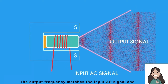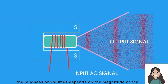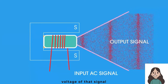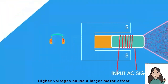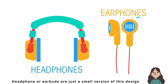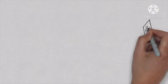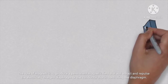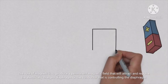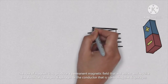The output frequency matches the input AC signal, and the loudness or volume depends on the magnitude of the voltage of that signal. Higher voltages cause a larger motor effect. Headphones or earbuds are just a small version of this design. They work on the same principle as this theory. Magnets are used to produce a permanent magnetic field that attracts and repels the electrically charged diaphragm or the conductor that is controlling the diaphragm.